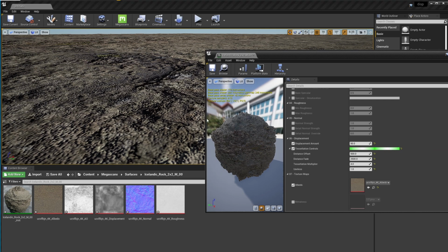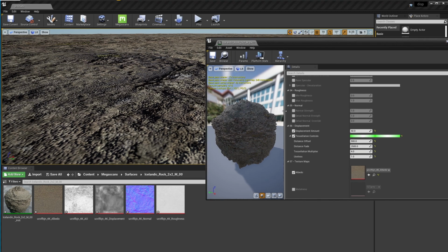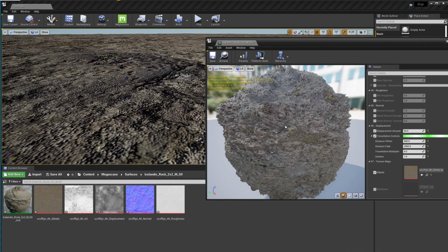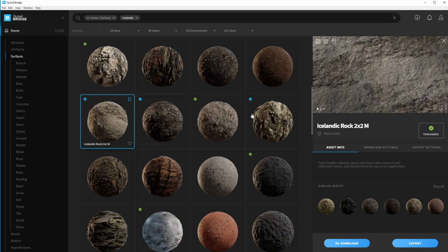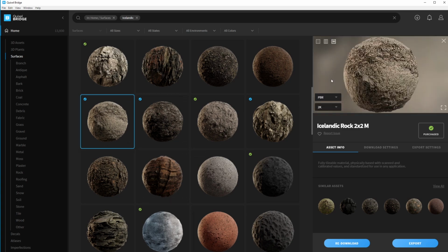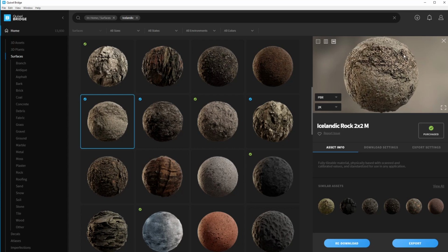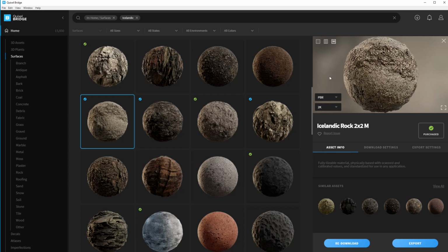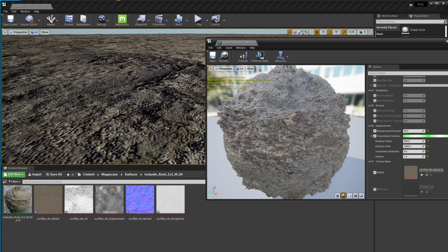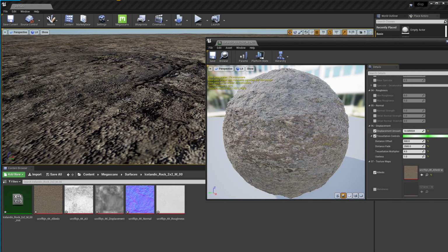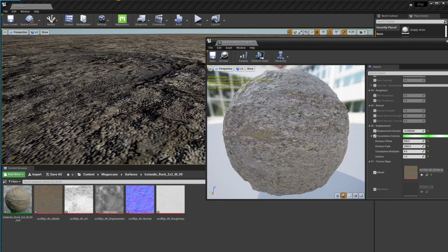distort. One of the tricks that I recommended in one of my videos is that whenever you're using displacement, the best way to get the displacement correct is to look at what's in Bridge. If we go here to Bridge, just click on the 3D and you're going to see how much that sphere is going to be displaced. If you try to approximate what you have in Unreal to what you see here, then you will get closer to the original. So let's get back into Unreal and dial that tessellation down until we get the same displacement that we had in Bridge, more or less.